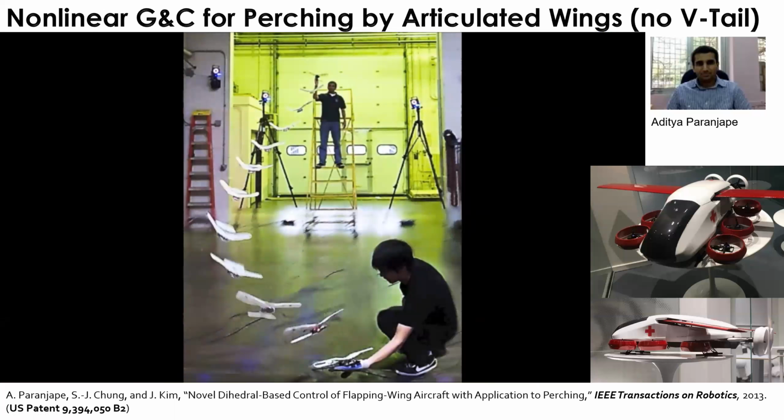Here, what if you have an external wind disturbance that is not perfectly dependent on your state, like velocity, speed, distance to the ground, or distance to the other neighbors? It's just wind blowing randomly, and it's not really state dependent. So you have to adapt your prediction of the disturbance in real time. It's called Neural Fly.